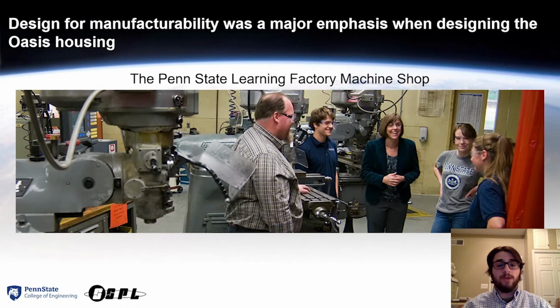When designing the Oasis payload, manufacturability was heavily emphasized. Following the DFM guidelines of faculty advisors, any interior corners found in the housing have been rounded to reduce milling cost. By rounding the inside corners, the housing is easier to machine. The standoffs are separate pieces and are screwed into the tap-through holes found in the bottom of the housing, rather than being milled as one piece. This way, less material is wasted when machining.